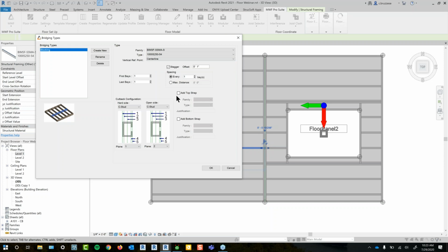And for anyone, again, who's used that line-based option in the walls, it's very, very similar. You just pick your family type. It is placed by marker line. So the marker line is going to hit the center of your joist. So it's basically if that line represents the center of your blocking, the top or the bottom. So you are able to shift the blocking laterally according to that line.